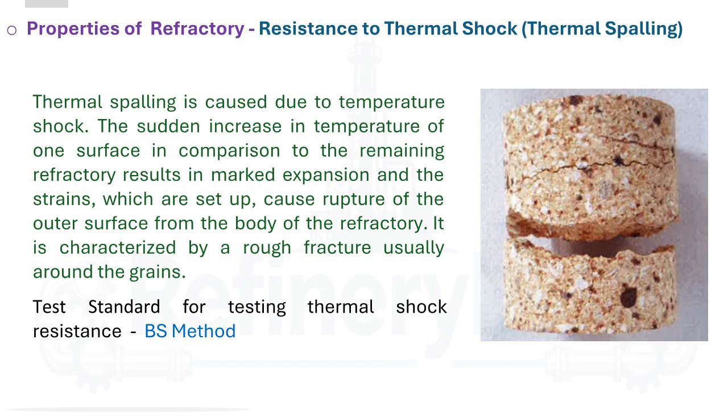Now let us look at the British Standard Method for testing thermal shock resistance. This test is designed to mimic the real stress a refractory faces inside a furnace. Imagine this: 3 prism-shaped specimens, each standing about 3 inches tall with a 2-inch square base, are placed carefully inside a cold furnace. The furnace begins to heat, slowly and steadily, until the specimens reach the test temperature over the course of 3 hours. Once they are hot, the temperature is held for half an hour, giving the bricks time to soak in the heat.